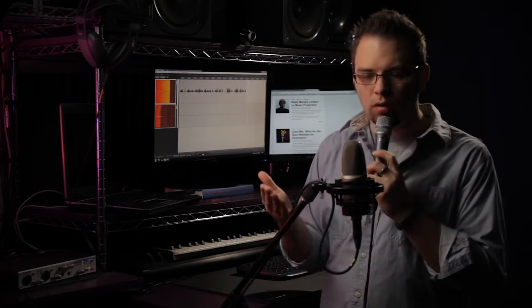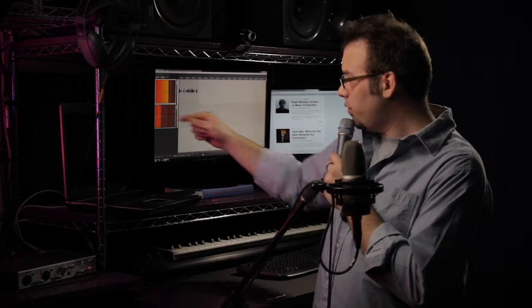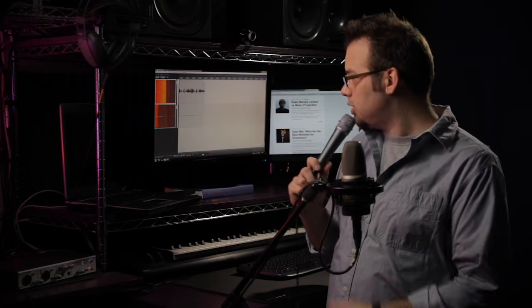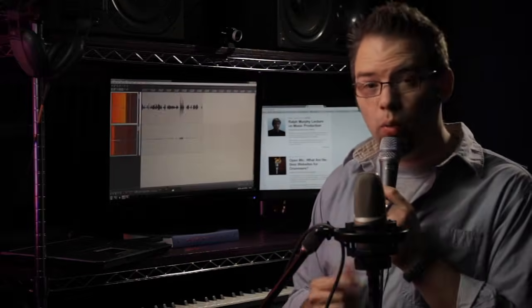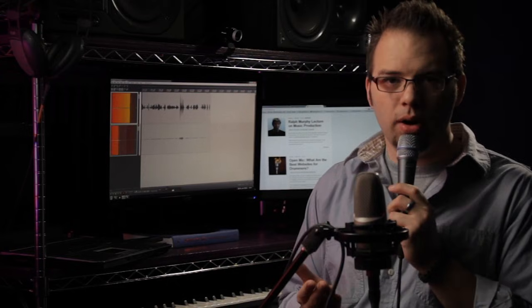Now, this microphone does have a more substantial, hotter output, which means it has more voltage at the same level compared to this dynamic microphone. But this microphone's further away. This microphone's right up against my face. And still, even if I get right on top of this microphone and shout right in it, 1, 2, 3, you're still only getting about -18 with the gain, which is not very much at all.